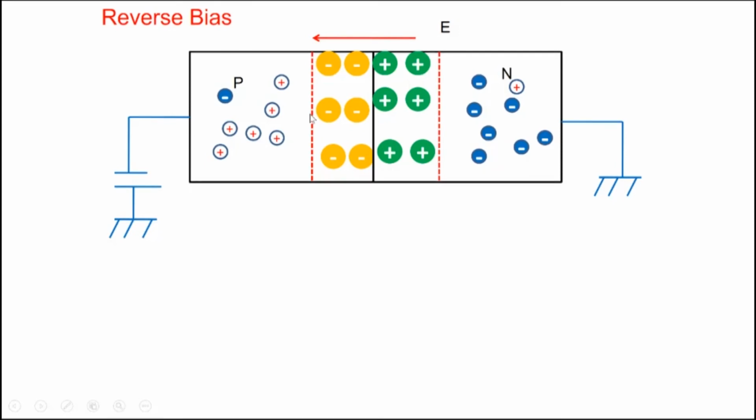Okay. And so now, because of this negative bias, you would like current to flow from left to right. Right? That's the direction of the current that the battery would require. And so basically, for holes, the holes have to flow from left to right to contribute to current like this. And the holes have to flow from right to left, and the electrons have to flow from left to right, to contribute to current in this direction, because electrons carry negative charge.